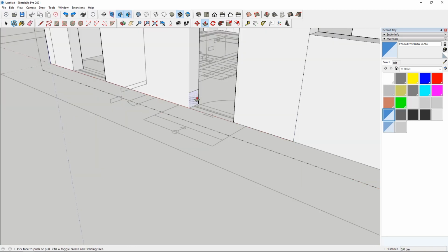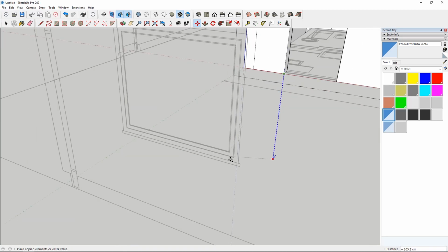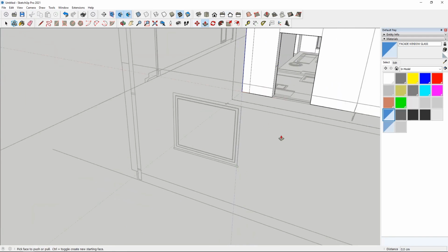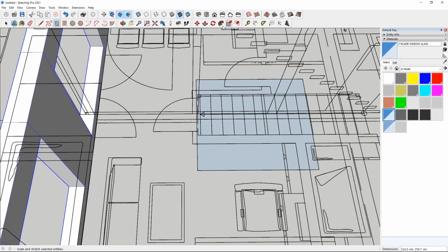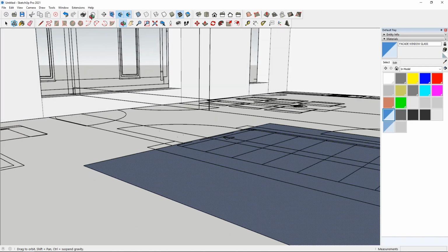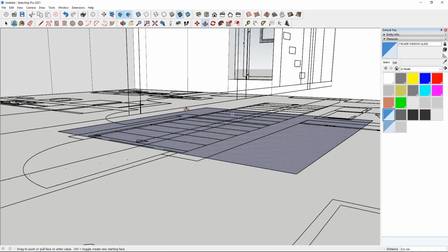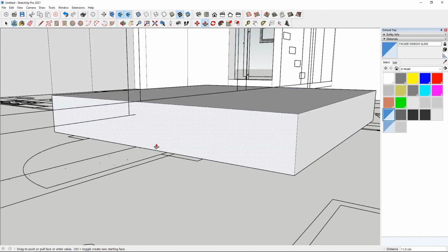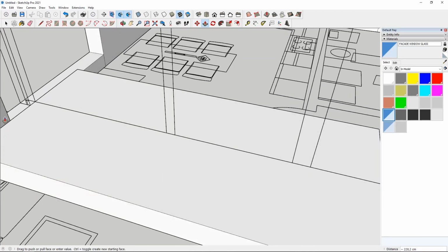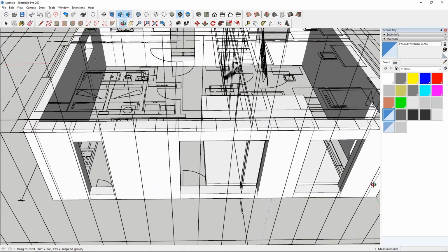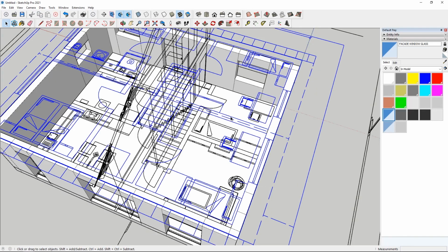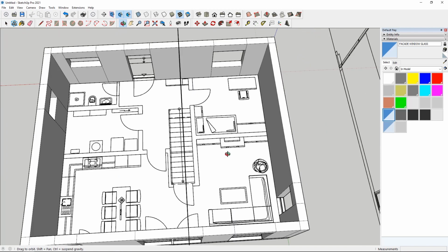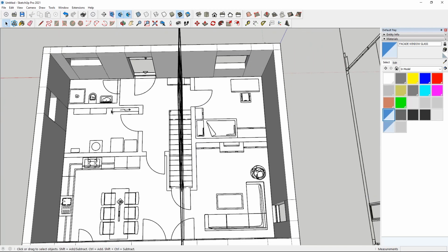Doing the exact same, we can create the lower part as well. With the outer walls in place, we can continue by modelling the floor as shown here. Remember to make it a group and move up the ground plane to floor height. Let's hide this attic plan for the time being and go on with modelling the interior walls.